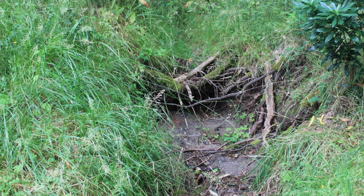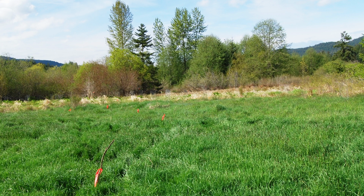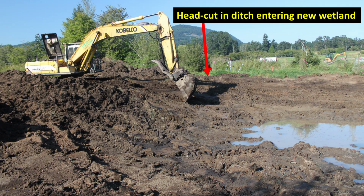A series of headcuts were present in the ditch where the wetlands would be built. Looking back, we should have measured the quantity of soil moving in the stream. We didn't do this because of the lack of funding, because no one wanted to delay the implementation of the project. We designed 4 wetlands to be built in a drained field that was dominated by reed canary grass. The orange-colored plastic ribbons marked the perimeter of one of the wetlands to be built. An excavator was used to build the wetlands. Each wetland was built by digging a large basin that was deepest in the middle. Water flowing in the ditch would enter and leave each wetland basin.